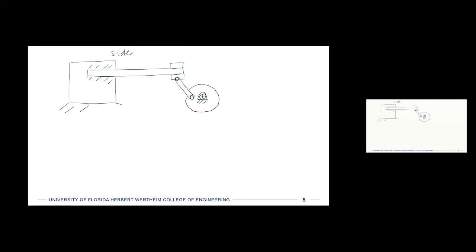As the wheel rotates, the connecting rod moves and causes the beam to bend up and down. So there's a reciprocating motion, and it's fully reversing, right? Instead of it being due to rotation, we have a flat specimen, and it just flips up and down like a diving board.